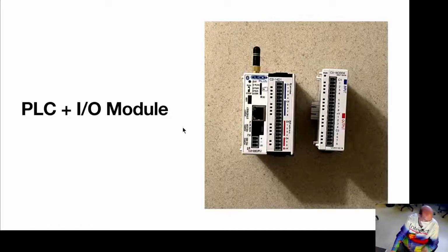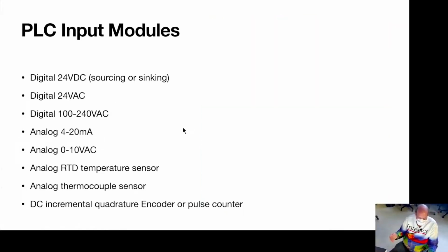So I was just describing I/O modules. Let's go over a list of some variety of input and then output modules. So digital 24-volt DC sinking or sourcing, which I'll explain in a bit. Or AC, where there's a little light inside that triggers a transistor inside. Or analog inputs, 0 to 10 volts AC, or 10 volts DC. There's that typo I missed. The Opta, for example, has 0 to 10 volt DC inputs. So I could connect a slide potentiometer, or buy a sensor that outputs 0 to 10 volts DC. I could have a VFD that outputs the current speed as 0 to 10 volts, or a temperature sensor, or a current clamp, or I have a laser distance sensor at work that outputs a distance in 0 to 10 volts. In industry, 4 to 20 milliamps is also slightly preferred, but more expensive.